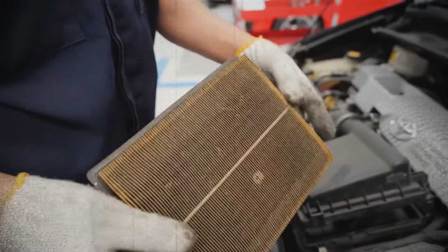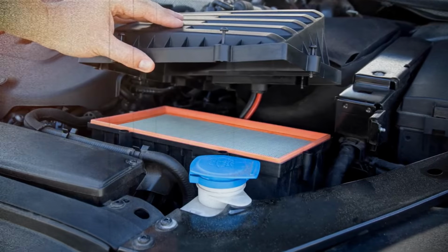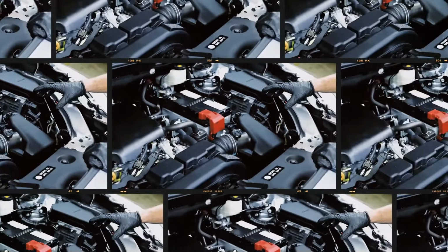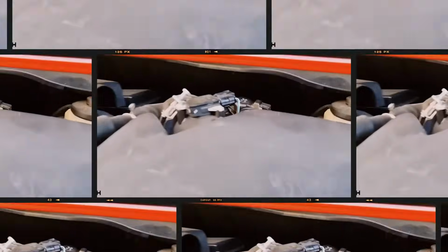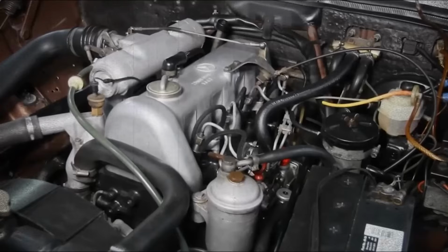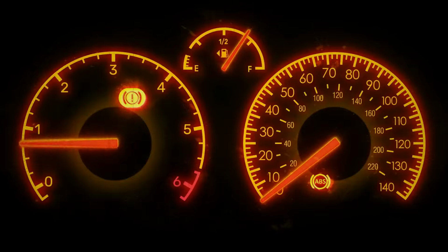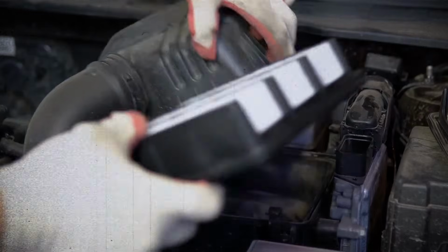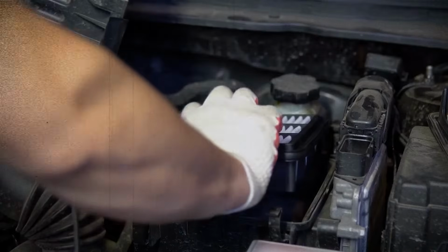A clogged air filter is another common cause. When the filter becomes dirty, it restricts airflow and increases turbulence, making it harder for the MAF sensor to take accurate readings. Damaged intake hoses or cracks between the air filter and throttle body have a similar effect. They disrupt the steady flow of air the sensor depends on.